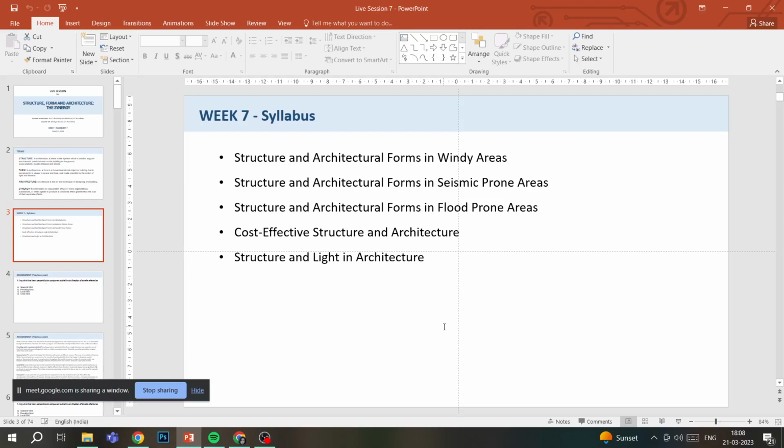The effects earthquake has on the earth: there is ground motion, and landslides can happen. Then the effects of earthquake on buildings, the kind of damage and destruction they can do, and what the main reasons of failure are in seismic prone areas, because there are a lot of structural reasons also why earthquake damages are severe. We can definitely avoid those kinds of severe damages if we pick up on those structure points. And then design considerations about earthquake, which depend on the size of the building, shape of the building, position of the building, and other things.